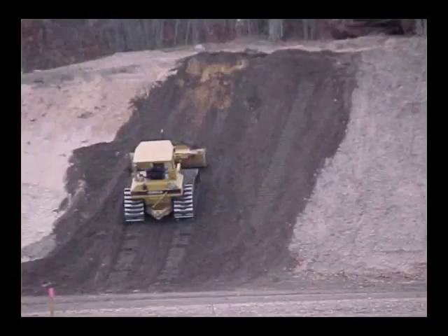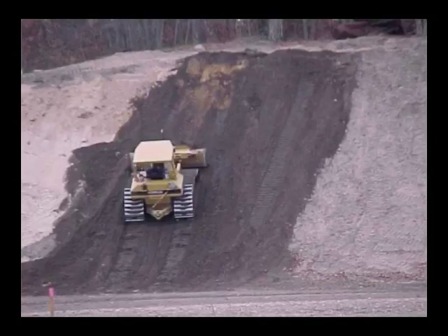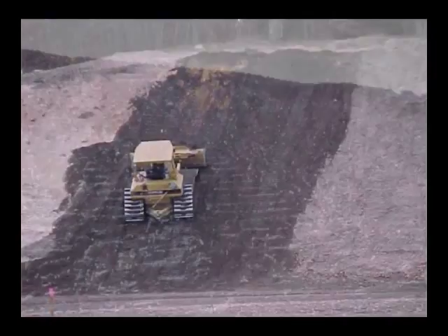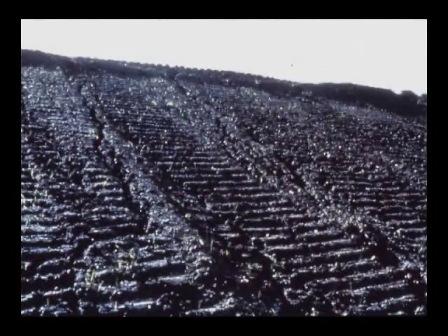Inspectors should ensure that the grooves are created perpendicular to the direction of runoff flow. Grooves can be created using a variety of equipment including discs, tillers, the teeth of a front loader bucket, or tracked vehicles. If a roughened surface is the final grade, seed and mulch should be installed within 5 days. Ensure that rilling or gullying has not broken through the roughened surface. It may be necessary to supplement the roughening with other SESC measures.